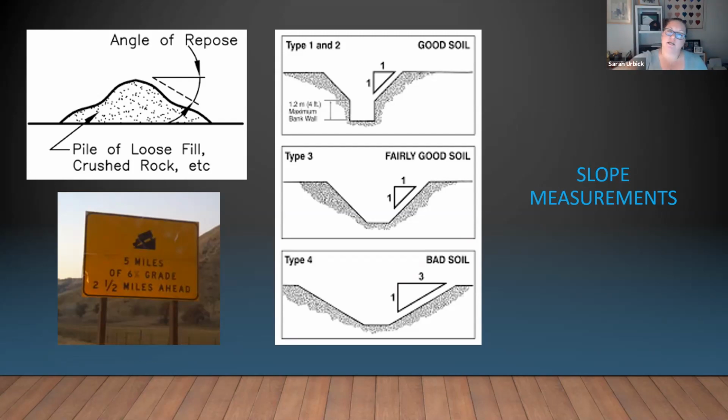We just let gravity do its job. So we will talk about having a trench that is a 1-to-1 trench or a 2-to-1 trench, but then perpendicular to this, the direction the pipe is going to go, that will have a slope that's going to be a percentage. So you never know when you're going to have to deal with both. You could end up with both of those on the job. Okay.